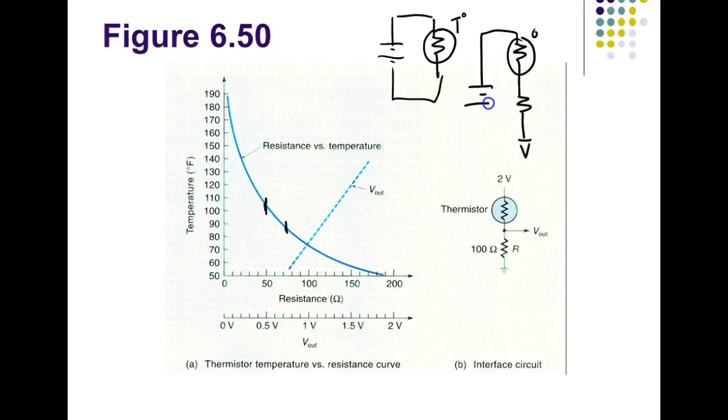And this is the way the sensor would actually be. So now as temp goes up, its opposition would go down, and the voltage drop across that resistor would go up, right? You understand? So I could sense across that resistor right there. And now the voltage is going to vary with temperature. If temperature goes up, the output voltage would go up. If the temperature goes down, the voltage goes down.